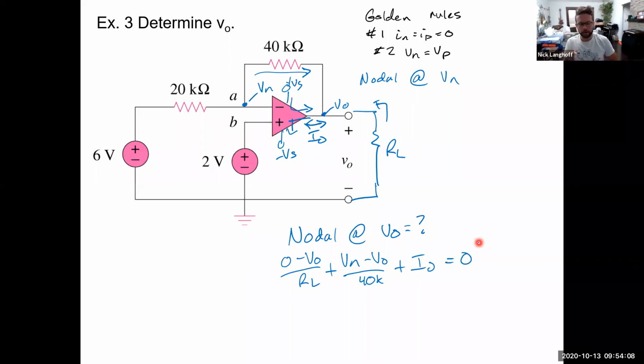The reason that this is such a problem is, remember that by op amp rule number 2, the op amp will provide whatever current is necessary, I out, to keep VN equal to VP. So you can't know what I out is. This equation doesn't get us anything useful at all, unless somehow you already knew I out. But remember, the amplifier will just provide whatever is needed.